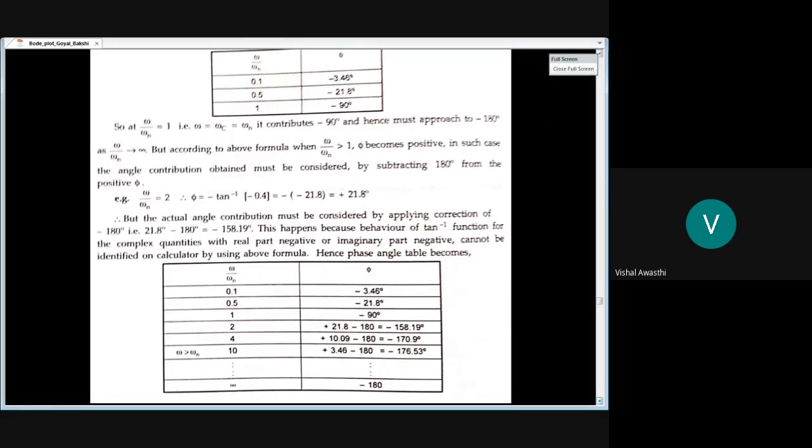So in considering your transfer function, we have gain, simple poles and simple zeros, poles and zeros at origin, and quadratic poles and quadratic zeros. When we have the idea of individual terms, we can combine these terms to concentrate on the different points, and we can construct the overall Bode plot.